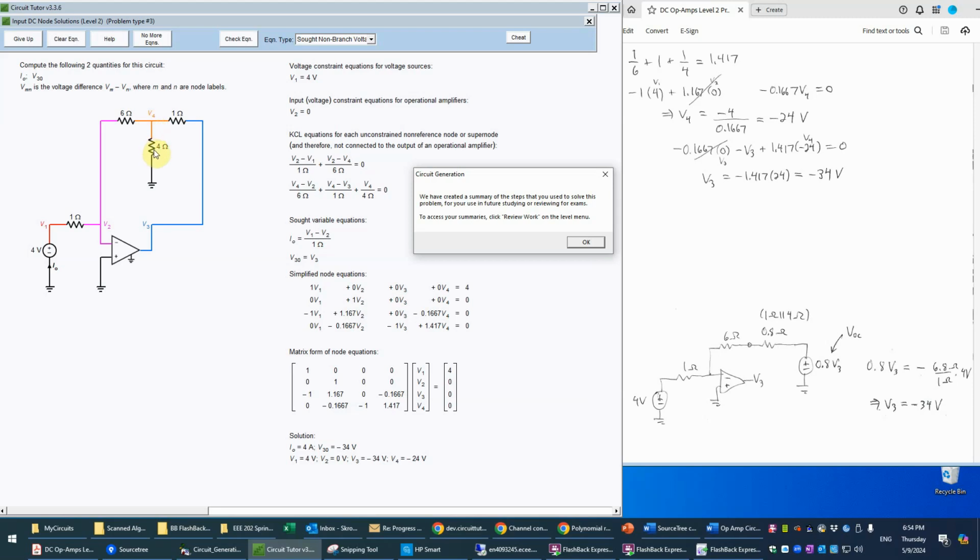So the voltage divider formula is the input voltage V3 times the resistor of interest, across which V4 exists. So that's 4 ohms divided by 4 ohms plus 1, meaning 5. And so that's basically 4/5. And so we get a factor of 0.8 times V3. That's the equivalent voltage source connected to ground to model this circuit.